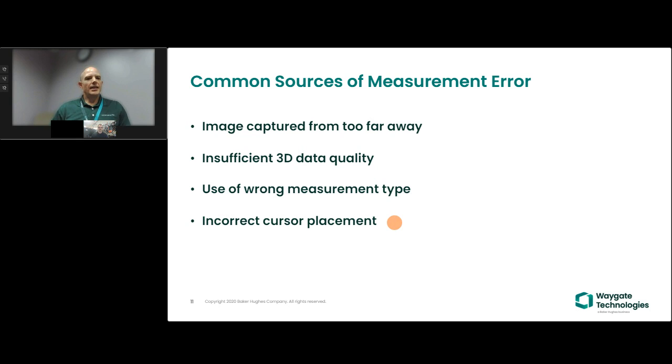And finally, incorrect cursor placement. Most of the surfaces that would be measured with our products are not just simple flat surfaces. They have complex 3D shapes. And so if you put your cursors in the wrong places, you will get an answer, but it may not be giving you the actual dimension you're interested in.